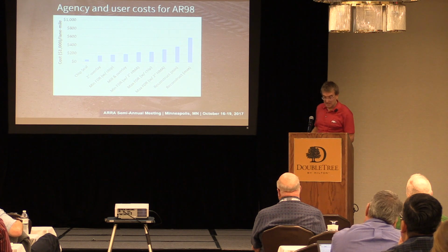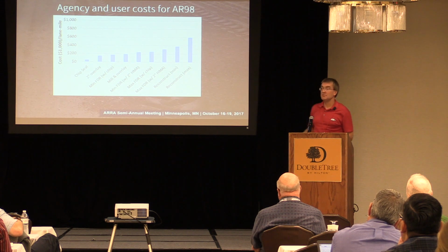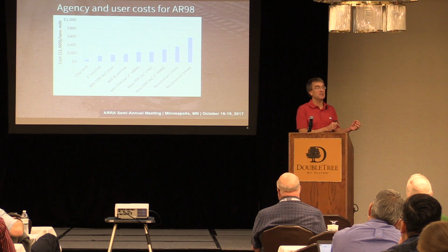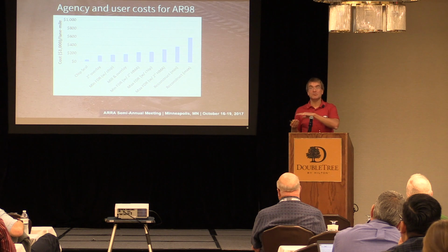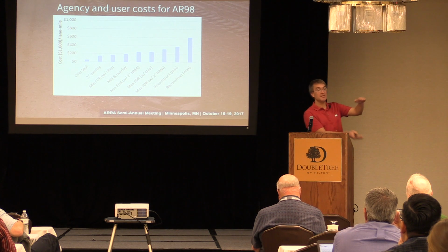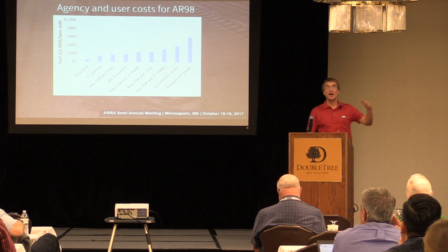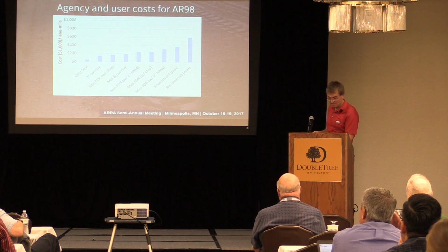And you can see here that we have min and max. And that's assuming a minimum structural number is one end. So that, I believe, was an 8-inch depth. And then a maximum, I think, was the 14. Maybe it was 6 and 14. But basically look at a minimal structural capacity and a maximum structural capacity. Obviously, the maximum structural capacity will cost more because it's thicker.